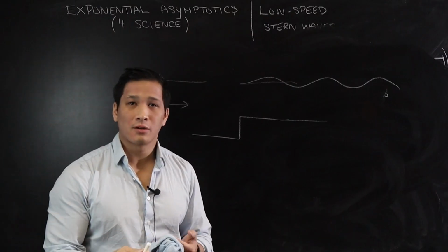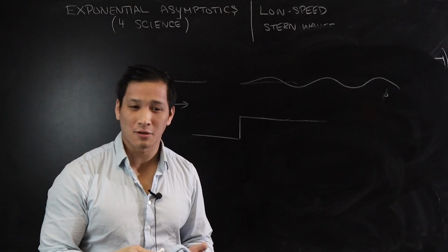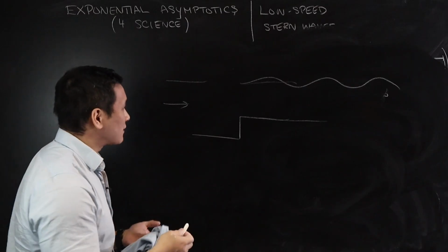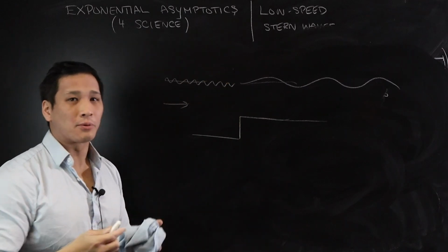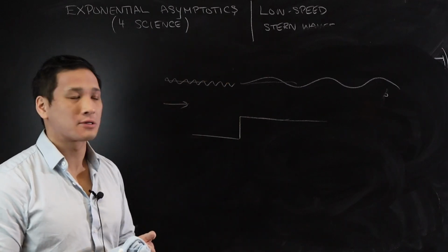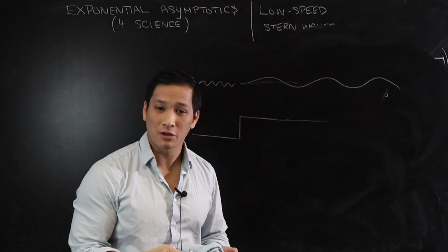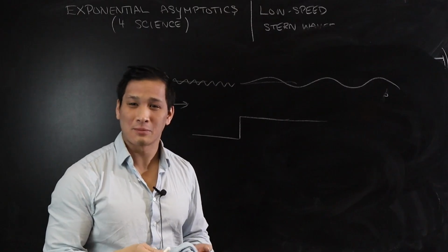But actually, your free surface equations should also involve a small amount of surface tension, right? Water includes surface tension, and the effect of surface tension is to produce small-scale ripples, little capillarity waves in your free surface, and those can be shown to also be exponentially small when the speed of the stream is small.